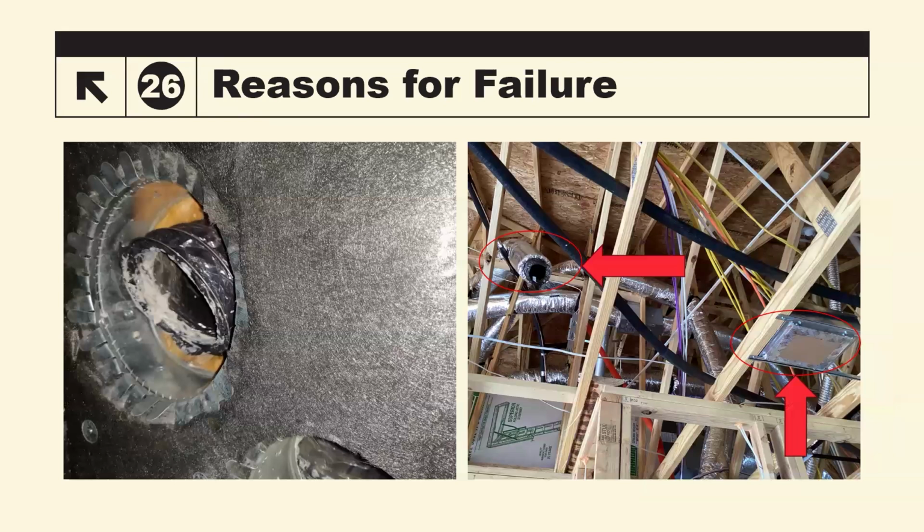And also another one, and again, incorrect duct size to collar size happens a lot more than you think, is they've got equipment on the truck. They're now putting in a 5-inch or a 6-inch duct, and all they have is an 8-inch collar. They're going to put that 8-inch collar in there and then just try to force the duct into it and just hope that nobody catches it. That's what you see happening on the left.